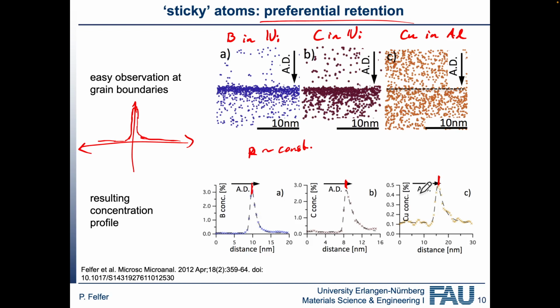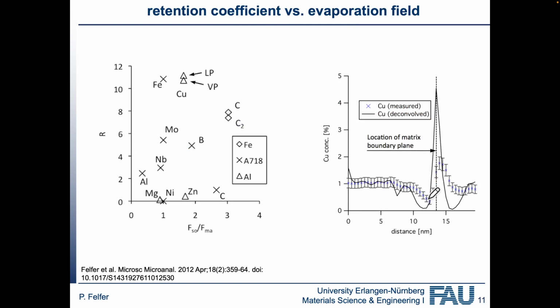But I, for example, have done it for copper and aluminium and other things in aluminium, where you then see a distribution that's much closer to what you would expect compared to what you observe. Because, for example, if you quench aluminium, you all know you have a precipitation-free zone, so you have some segregation just goes straight into the grain boundary. The atoms that segregate need to come from somewhere, so you should have a few more atoms around than you have in the middle. And if that's not observed, then it's probably a problem with the measurement. Or if it's only observed on one side, it's probably a problem with the measurement. And that's exactly what that is here.